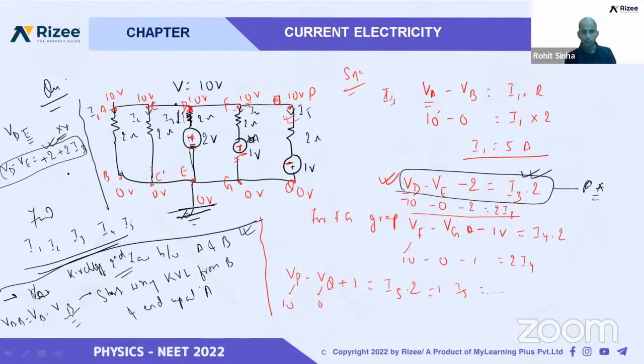Okay, I use this technique of Kirchhoff's voltage law for this point also, for PQ also. You can write like this for PQ. I'm writing here the last equation, for PQ, P minus Q. It means start from Q and reach at P, moving in this direction. We see that we are moving from high potential to low potential, that means we have to write minus of 1.